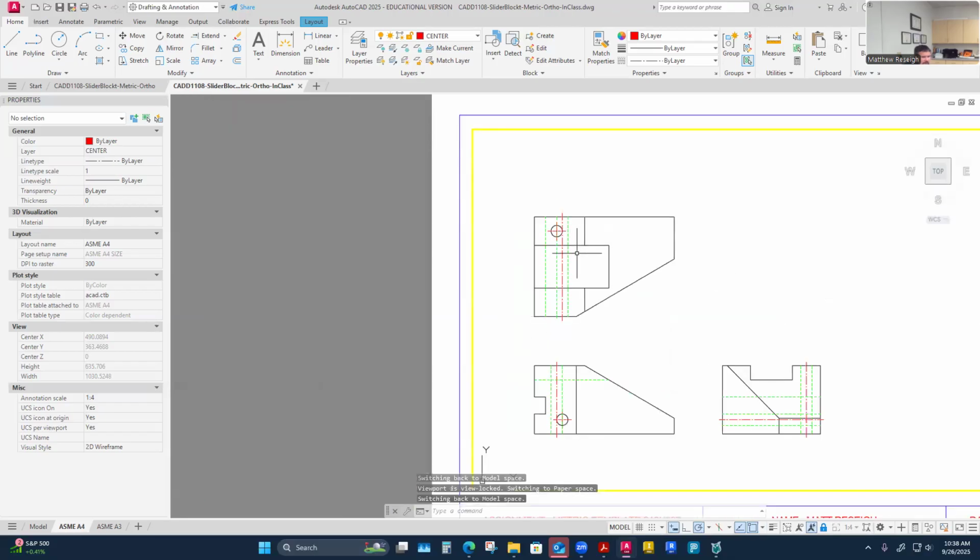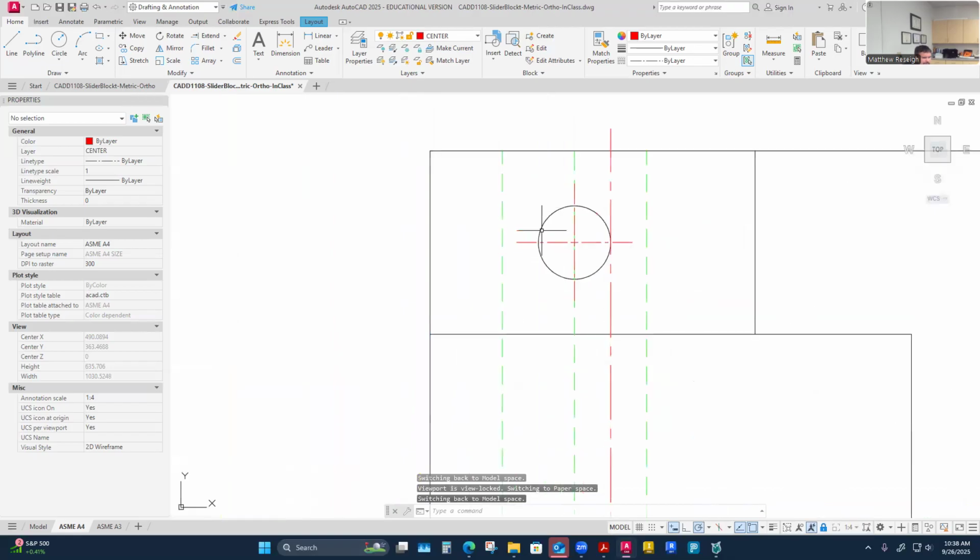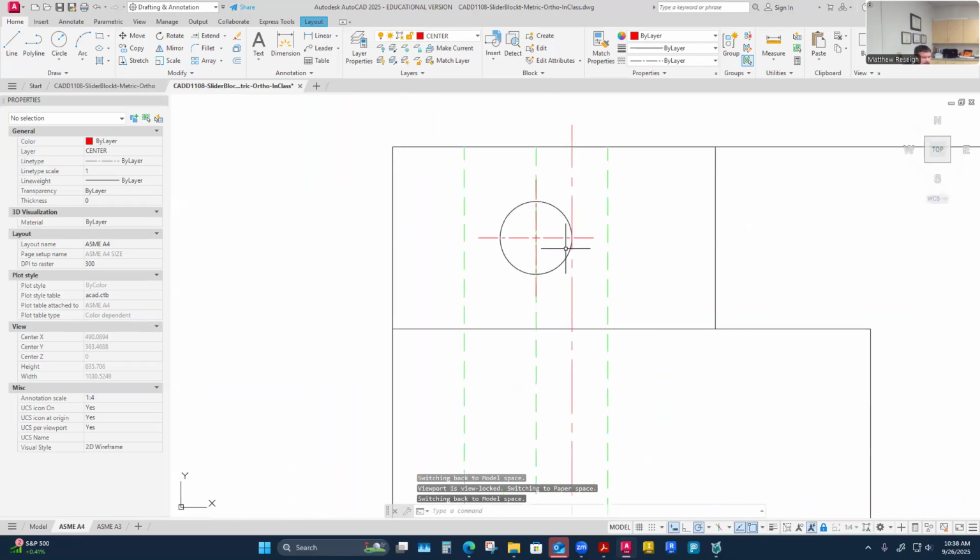Yeah, I think that's fine. That's the only thing I'll ever say. I know on our rubric it will say line type scales, and I only will usually make a comment if those just look like solid lines or whatever. But I feel like sometimes on center marks when they're small like this, you may keep checking. Don't beat yourself up too much to find one that finally breaks up. If our marks are really small and the line type scale just can't quite break it up, that's okay on a small center mark like this.